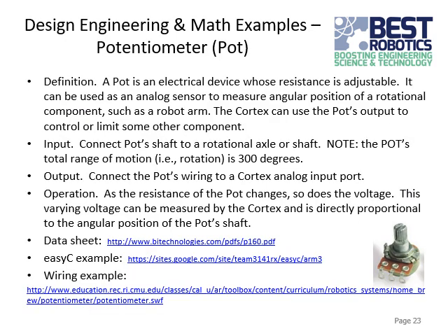Here I just wanted to tell you about another part you have at your disposal, the potentiometer. I wanted to highlight this one because it doesn't get a lot of use, but it can be useful at times. I think a lot of people don't understand it very well, so I wanted to talk about it. Some people just call it a pot for short. It's a device whose resistance changes as you turn the knob on it. And so you can use it to make an analog sensor that can measure the angular position of something that rotates, like a robot arm.